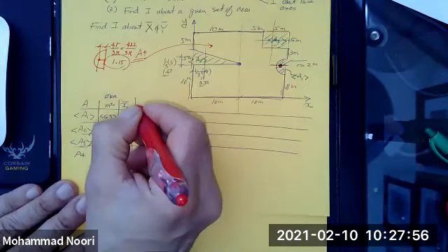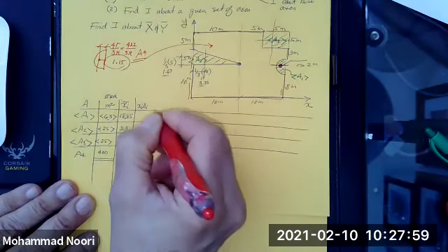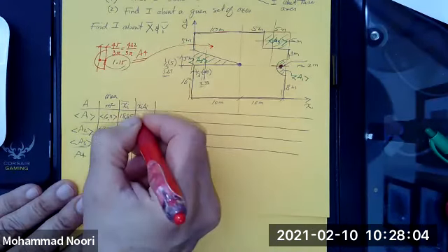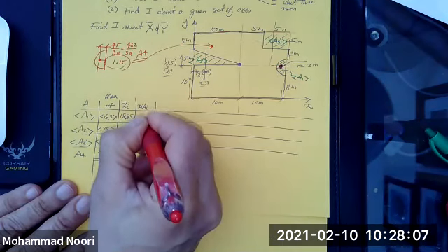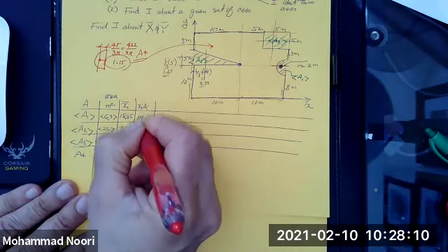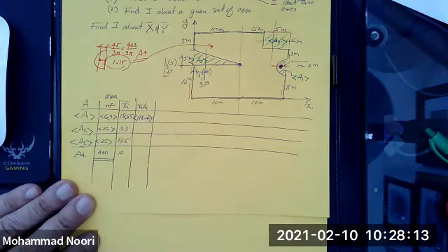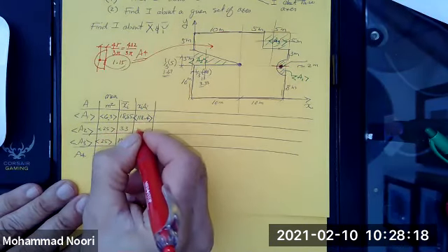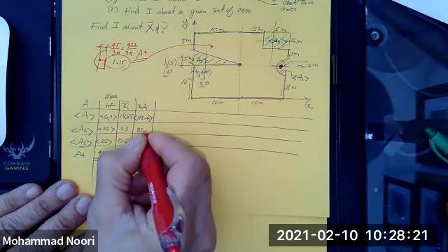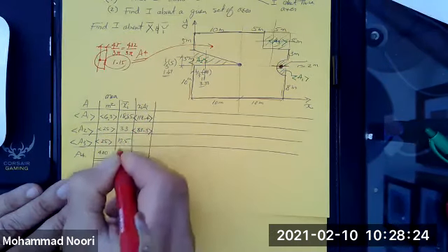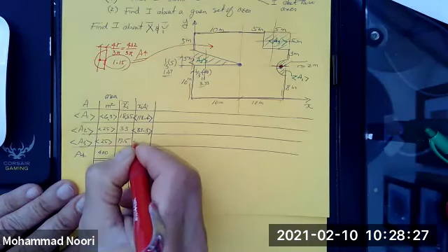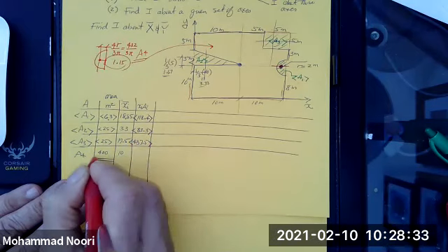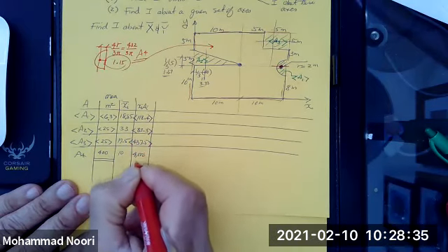Now, the next column, you remember, xiAi. So just multiply this by the corresponding area. So this would be 118.4. Area is negative, so this would be a negative value. This would be the product of these two, 83.3, and that is negative. 17.5 times that, 437.5, also negative. And this one, 10 times that, 4,000.